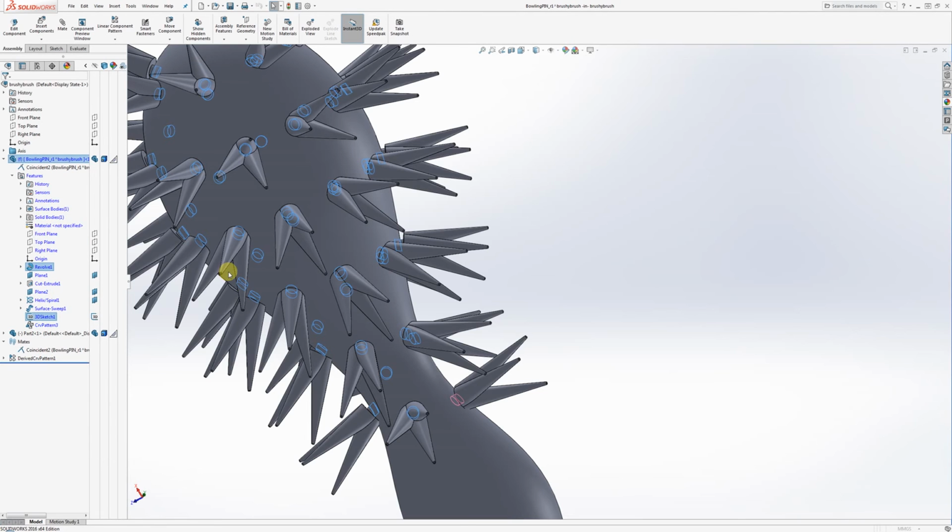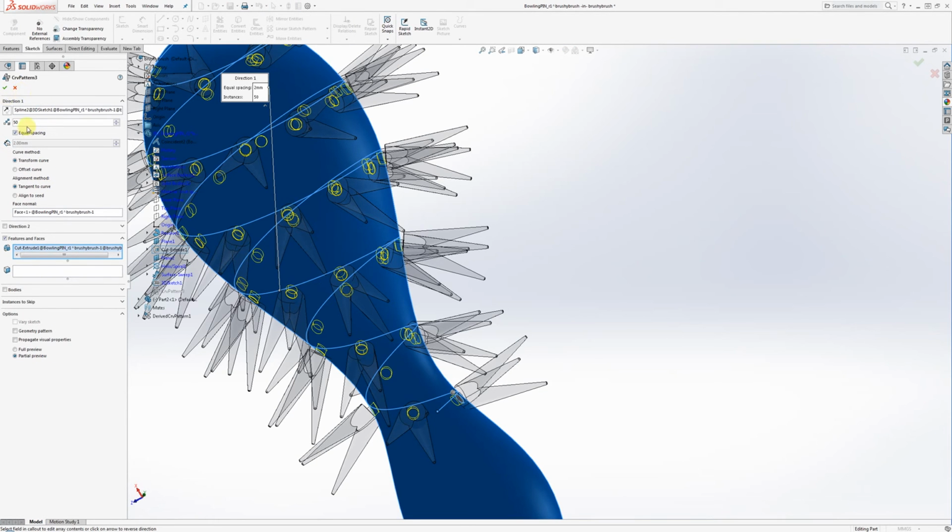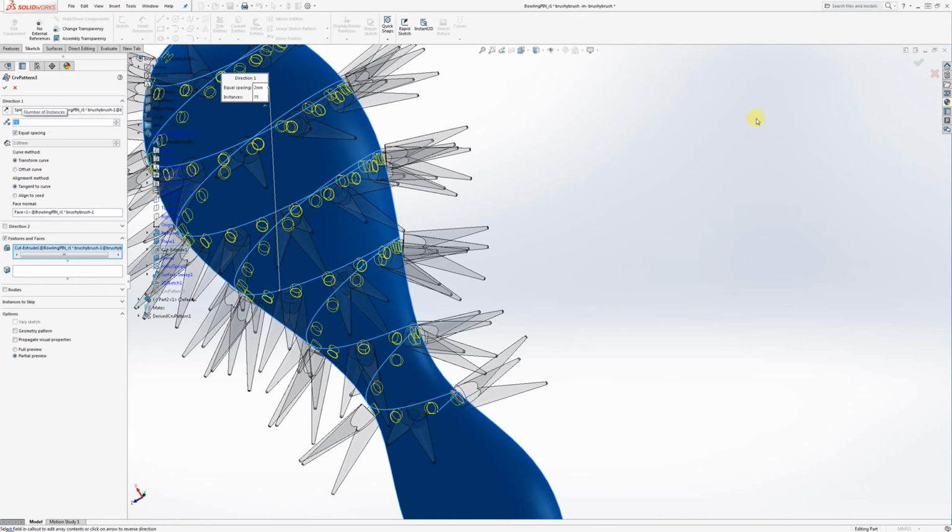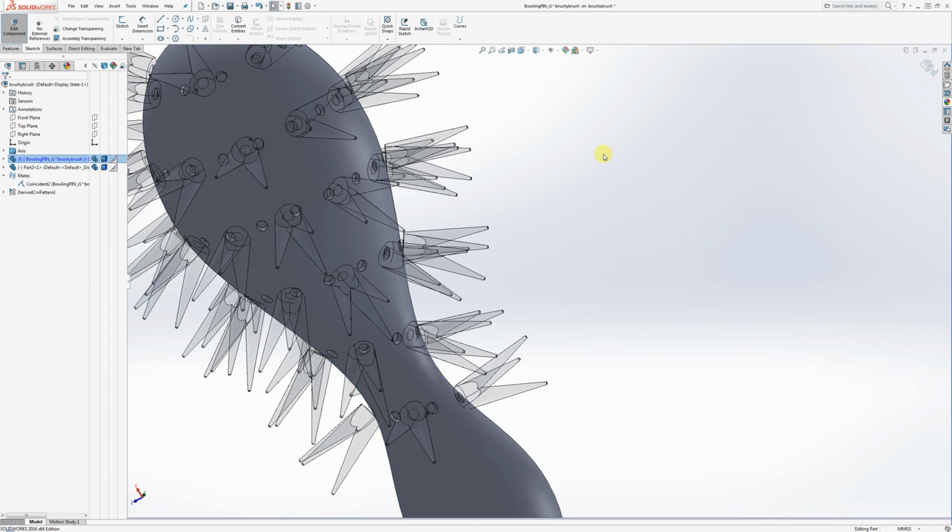confirm that I like all of this, but I can do something wild like, what if I added 25 more instances into the pattern itself? Let's approve that. Let's see if it fails. So the pattern's going to update, okay, but we need to go back to the component, or to the pattern-driven component, and update that. So the pattern's updated.